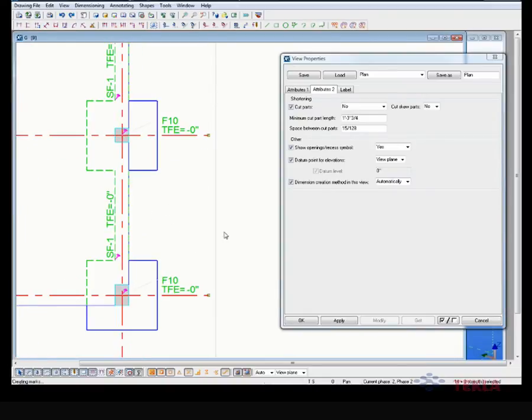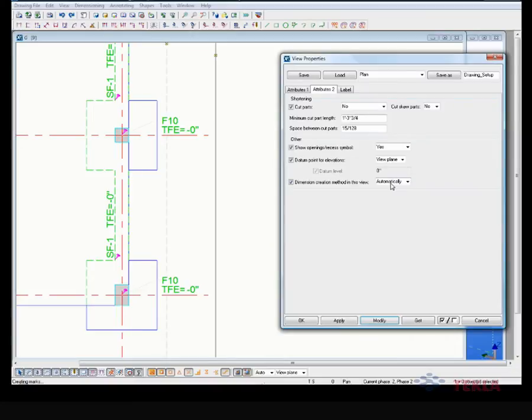So we can see everything is at 0. Well, that's because in the model it was created at 0 elevation, so it's showing its absolute. But if I come here to datum point elevations, I can put in here -1,000 feet, and that will use that as a